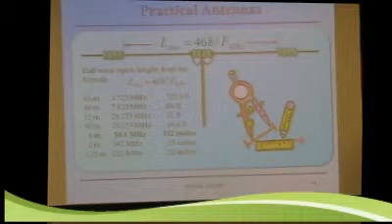And that gives you the length of a half-wave dipole in feet. So it's just 468 divided by the frequency, and 468 is easy to remember. These are some calculated dipole lengths done for you. So you see at 80 meters, 3.725 megahertz, that's 125.6 feet, etc. Now, I just told you 19.25 inches.